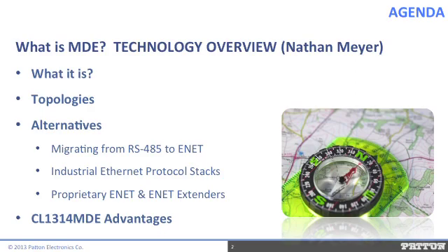In my portion of the webinar, I'll discuss Ethernet in the context of MDE, that is multi-drop Ethernet. It will include what MDE is, its topologies, the migration from legacy serial deployment to industrial Ethernet, issues with proprietary Ethernet, and finally, the advantages in using MDE devices. MDE simply means multi-drop Ethernet.